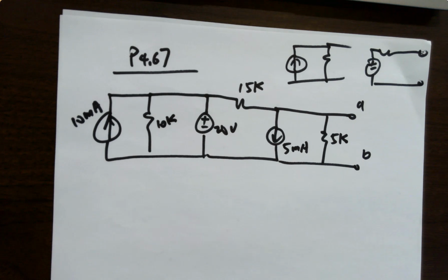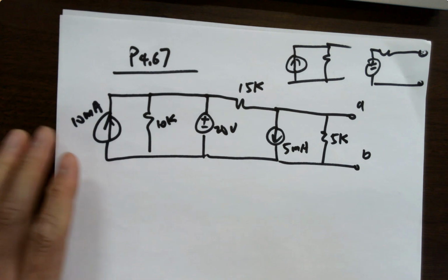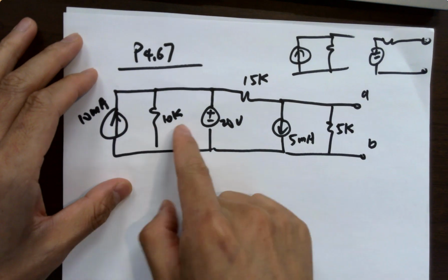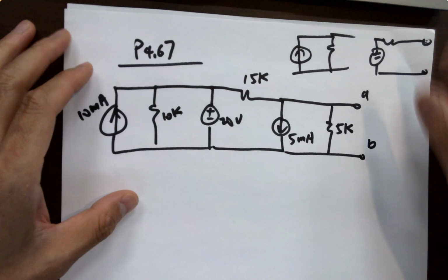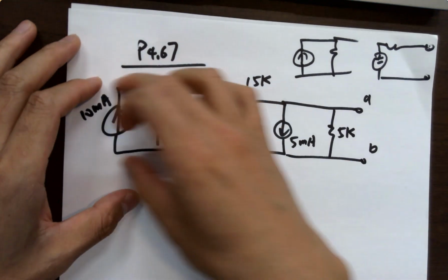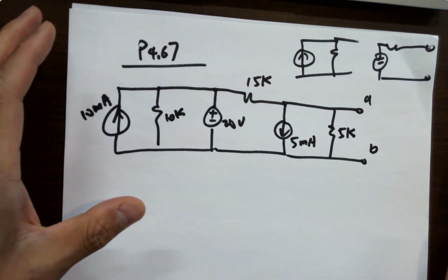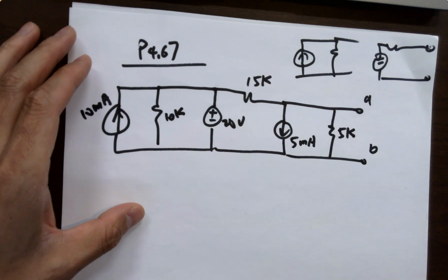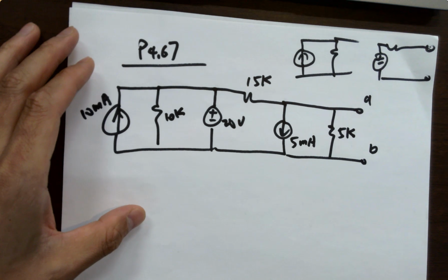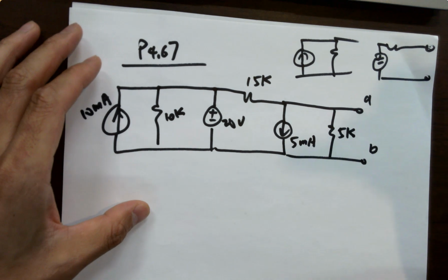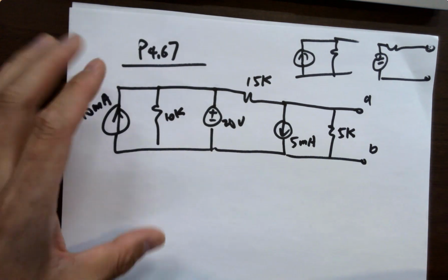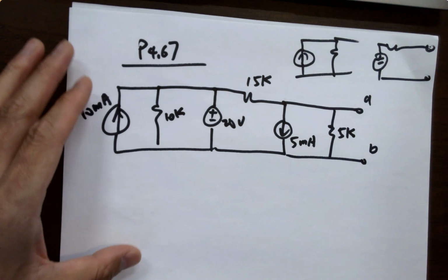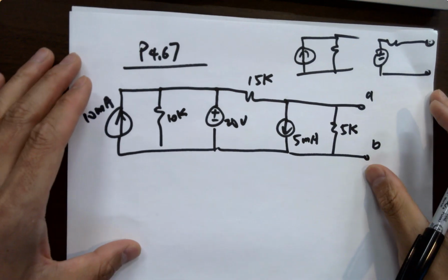So Storm visited. He was asking me to run through this, and I converted using the source transformation. So this is another lesson to learn. Whenever you don't know what you're doing, you always make a mistake because you don't know if that's right or not. It's just following whatever the tutorial told you to do. But the limitation is not documented. It didn't tell you that when you have a voltage source shorting these two networks, you shouldn't use source transformation. It doesn't work anymore. But it didn't tell you. So I found that out this morning.